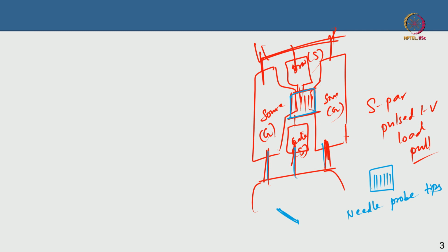Okay, and it is not a waveguide per se. You need a waveguide to measure RF devices. So either you can use a microstrip or a strip line. Those are more complicated to implement in this kind of a transistor geometry, especially for on-wafer measurement. CPW, this kind of a coplanar waveguide, or a GSG is more convenient to implement. However, strip line and microstrips are very widely used in MMIC design, not for enabling on-wafer measurement, but for actually implementing certain functionalities in the circuit. They are very much useful. You need to have this waveguide. So that's the reason you have this CPW.